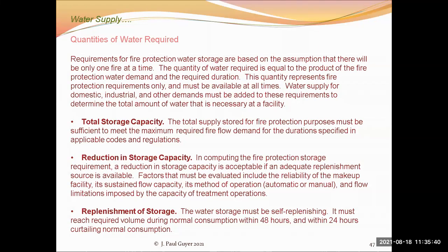So with a water sprinkler system, you need to have enough pressure at the head. And so you calculate the pressure requirement and size your piping for the most hydraulically remote location in the building. That's the sprinkler head that is furthest from the point where the water enters the building. So if you're getting the water from your municipal utility, and if they tell you that we can deliver water to your building at 50 PSI.